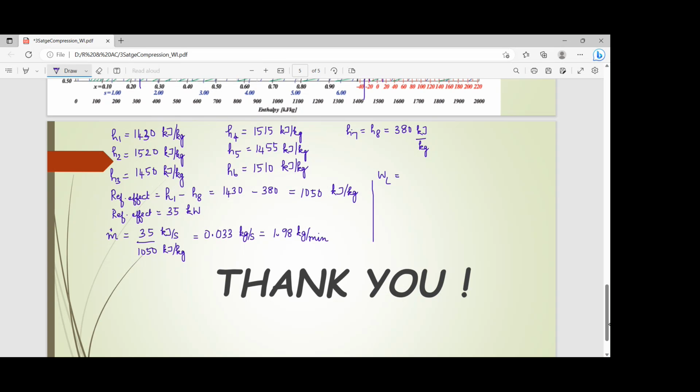So the low pressure compressor operates between 1 and 2, so it is H2 minus H1. H2 minus H1 is 1520 minus 1430, which is simply, I think, 90 kilojoule per kilogram. Then the intermediate compressor, so that is H4 minus H3. H4 is 1515 minus 1450.